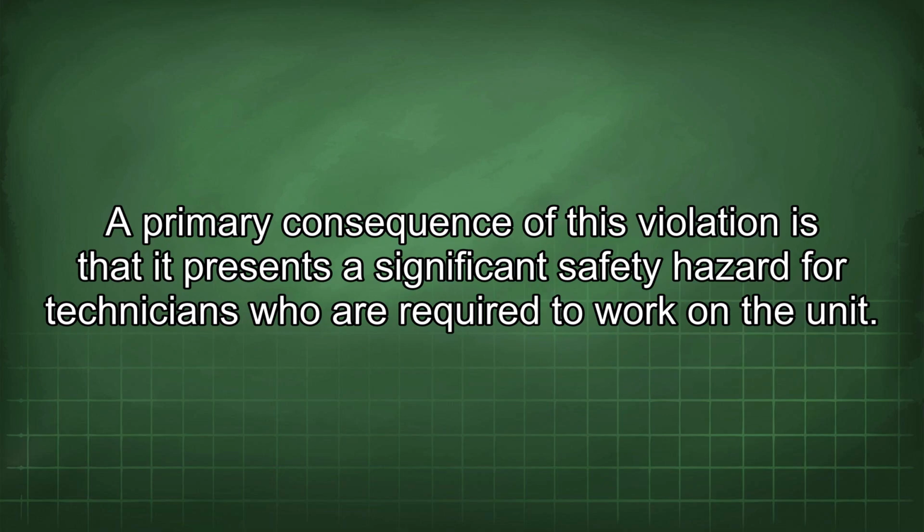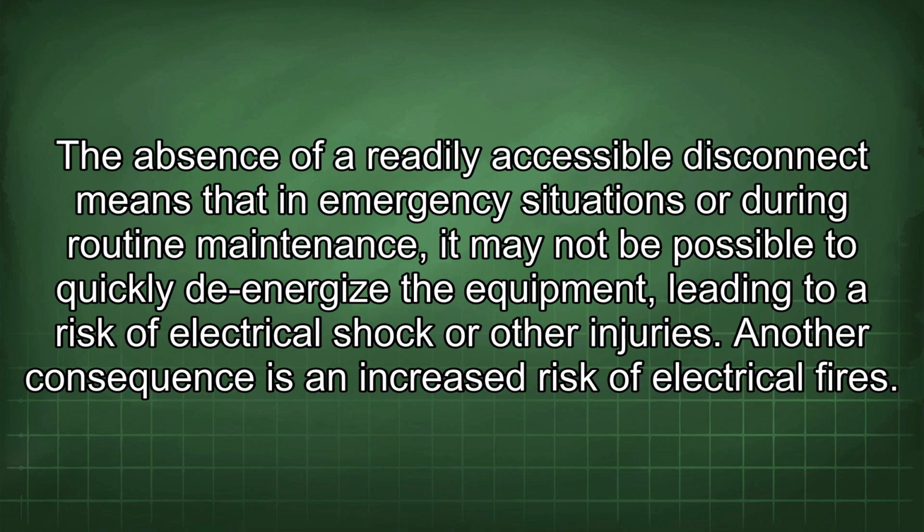A primary consequence of this violation is that it presents a significant safety hazard for technicians who are required to work on the unit. The absence of a readily accessible disconnect means that in emergency situations or during routine maintenance, it may not be possible to quickly de-energize the equipment, leading to a risk of electrical shock or other injuries.